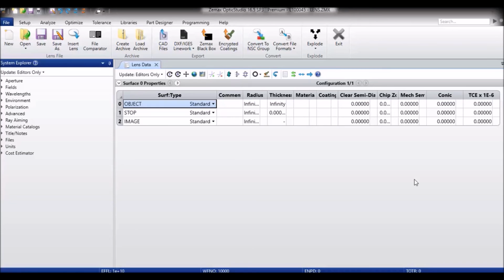One important category of optical systems is one that is basically sequential, but can also contain other elements that require a much more complex non-sequential ray trace. If you have a system like this, you would need to set up a sequential system so that rays can start on a sequential object and finish at a sequential image plane, but in between, rays can also go through any number of non-sequential components. And over the course of this webinar, I will show you how to set up such a system.